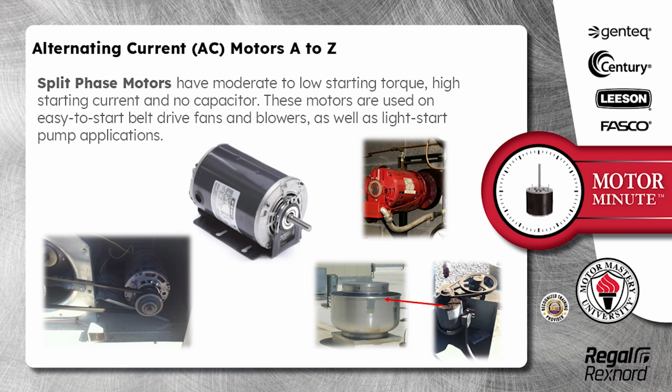Split-phase motors have moderate to low starting torque, high starting current, and no capacitor. These motors are used on easy-to-start belt drive fans and blowers, as well as light-start pump applications.